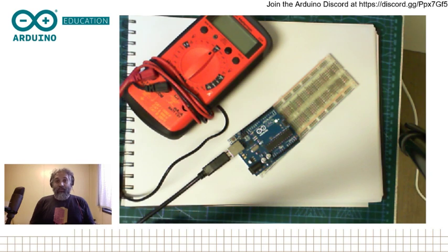This is very confusing for people. They think you can measure all of the 3 things everywhere, and that's not really how you work. When you measure components, you typically never measure the resistance. You definitely never measure the current. The thing you always measure is voltage, to see that the voltage arrives at the place at the expected value.